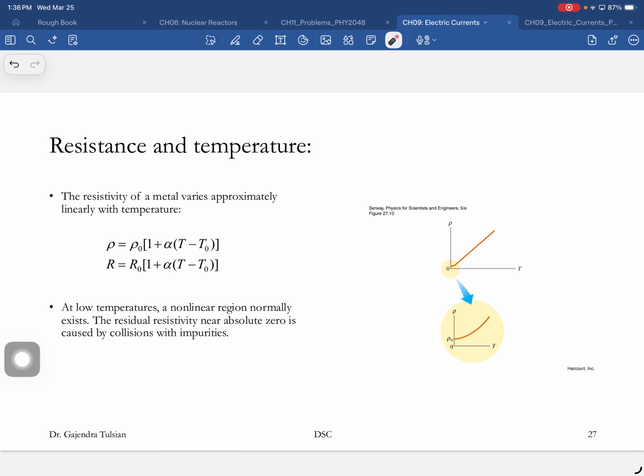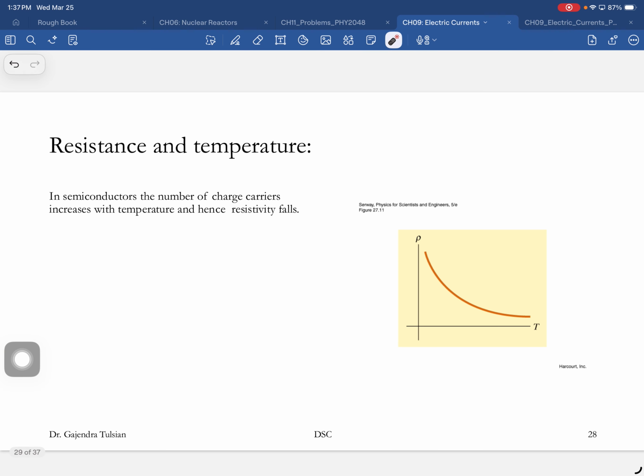I mean, very good, David. So resistance is caused by you bumping into atoms, and you're bumping into atoms more often. Okay? So that's why resistance increases. Okay, and as resistance increases, then you're converting electrical energy to heat faster. Okay? All right, so as temperature decreases, resistance decreases. For all metals, even at absolute zero, there's residual resistivity. Okay? For semiconductors, as temperature increases, the resistance decreases.